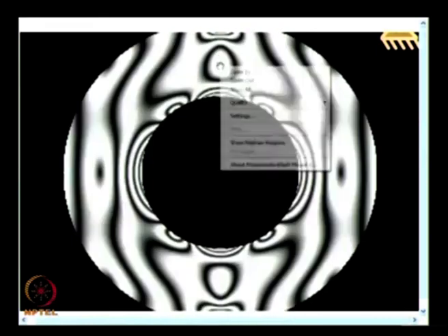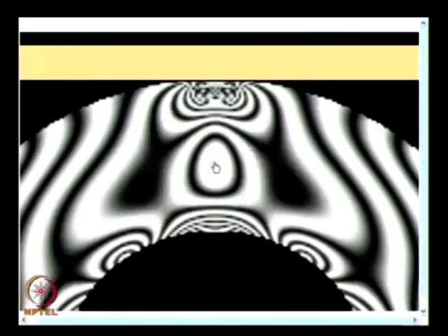And we had seen in the last class a particular feature, what happens in these types of zones. The fringe vanishes at this point. As the load is increased, fringes appear and they vanish at this point. And I said, akin to your fluid mechanics, you could call these points sinks.